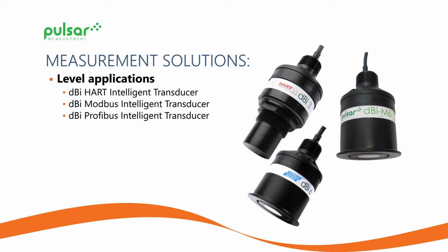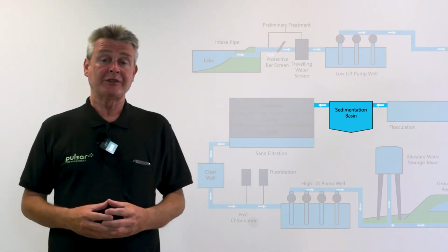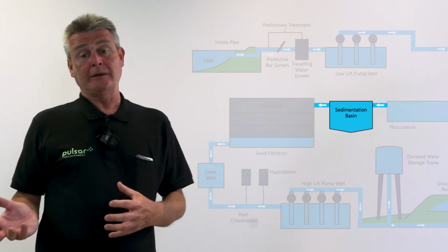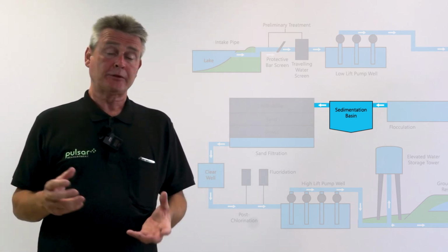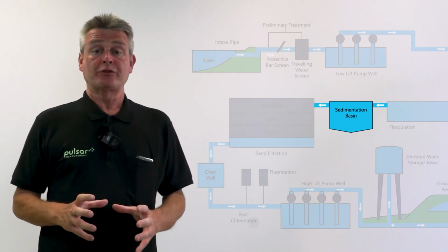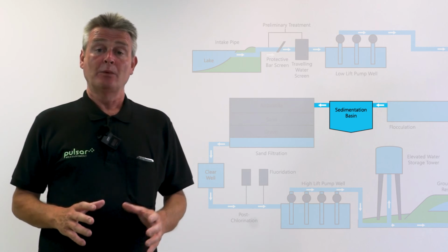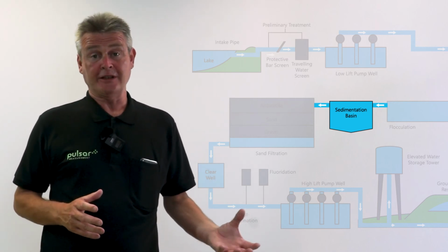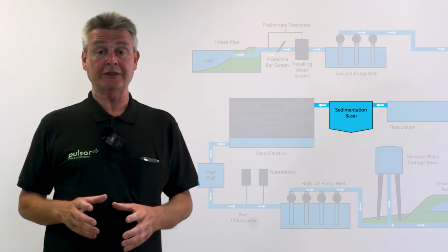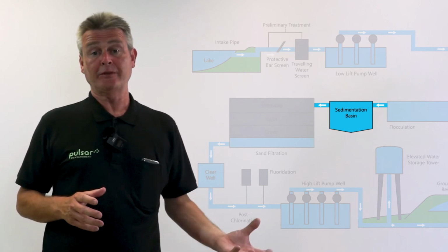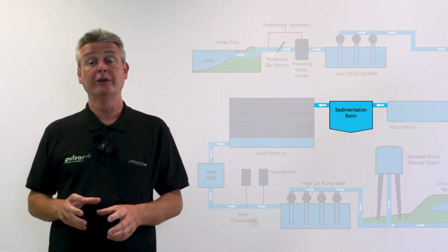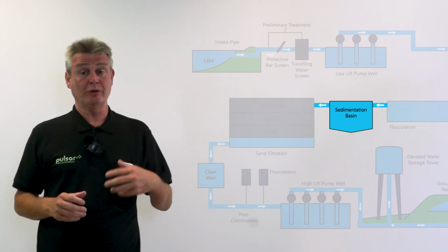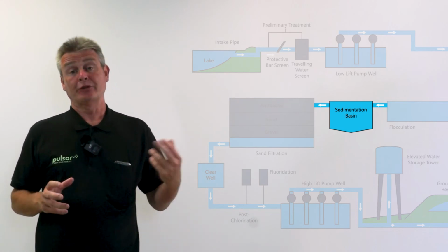One of the most important processes within the clean water cycle is the sedimentation. This is where we take out the solids from the clean water processing cycle. So post-flocculation, we're monitoring a settlement process where we're taking out the solids before they're passed on to the filtration stage. And it's important that we do take out those solids, otherwise that could lead to problems further down the line in the filtration itself, whereby we're having to use much more energy and electricity to backwash the cycle itself.